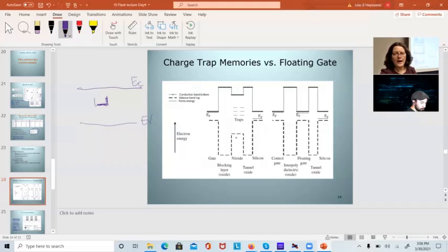This is called a trap. And this is the reason why ReRAM conducts current, even though it's a capacitor, when it's pristine. Now, if somehow I get an electron in this trap, it can stay there. Some of these traps have decay rates of like seconds.